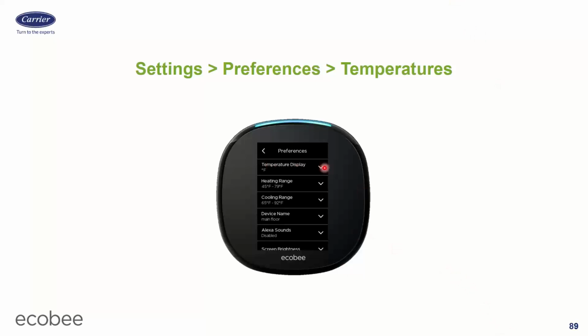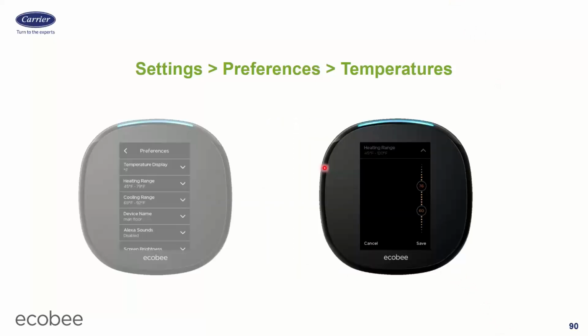So temperature display, Fahrenheit or Celsius, that's self-explanatory. The heating range, I think that range is pretty wide. 45 degrees. I don't want my customers setting this house down to 45 degrees unless they really, really want to. So I usually bump that up to something else, typically 55 or maybe 60 degrees. If it's your own house, you may want to have a really tight range on there so your family doesn't get crazy with it, right?